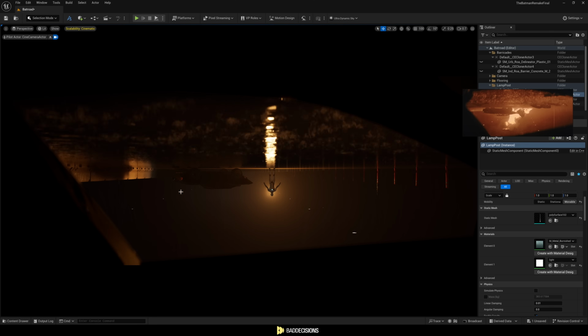At this point, we realize that our highway lamp lights are so small on the screen that sometimes they look like artifacts. That's simply because Unreal Engine only has a few pixels to guess how the light should look like. And that's something that usually happens with Lumen, so we can fix it by simply enlarging the light.